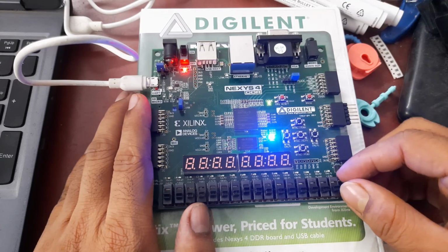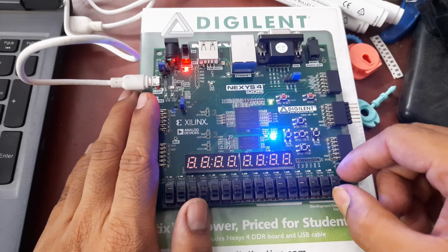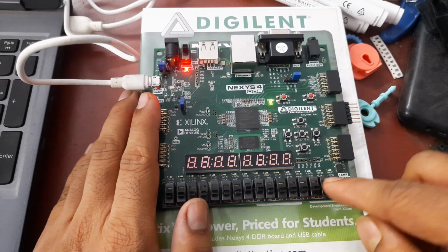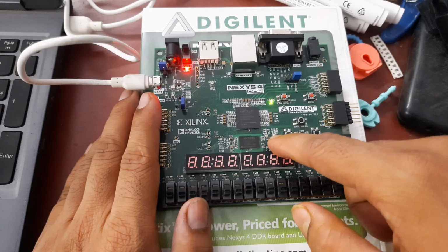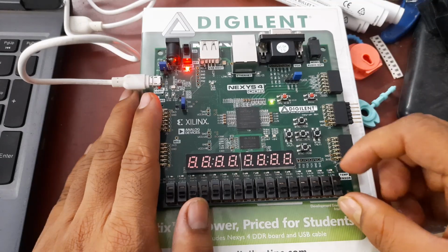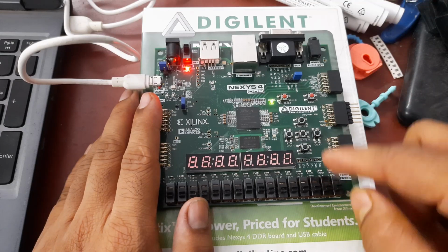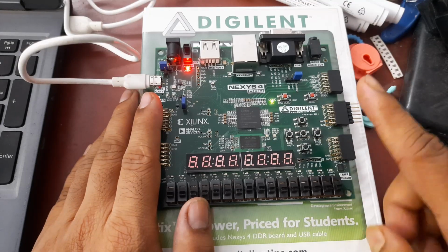Next, when I reset the thing, if I do the reset by taking R is equal to 1, right? This is R is equal to 1, therefore we see the LED in reset condition. Now when I make it 0 again, so S and R both are 0, it retains the last condition, which is basically LED off, right?